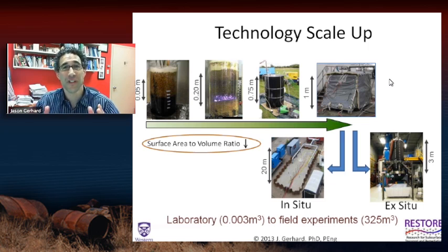And if you get too much heat loss, for example, to the outside world, it simply dies. So at this scale, you can imagine that we're having heat losses through this outside surface. And so the surface area to volume ratio is a very important one for smoldering. If it's too high, if there's too much surface area, you have too much heat loss and the reaction goes out. So this is a very difficult scale to smolder something, basically.